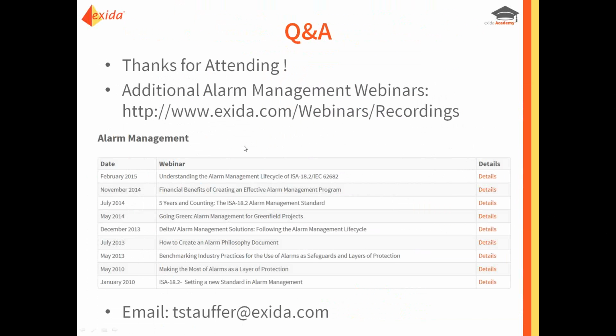So safety alarms are a more discrete set of alarms than IPL alarms. So some IPL alarms could be treated as safety alarms. It depends, essentially, on how important they are.